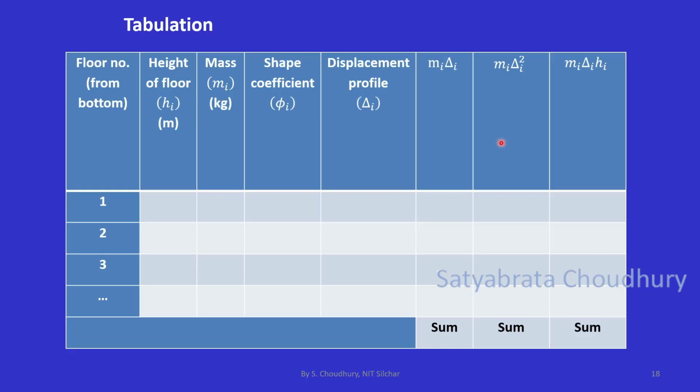beams. So certainly this will require some iteration, because after design you may see it is not matching with your desired percentage steel, then you have to adjust it, then redesign it, reevaluate it, again carry out the nonlinear time history analysis and see if it is satisfied. So for the purpose of tabulating the values, you have to use this table.